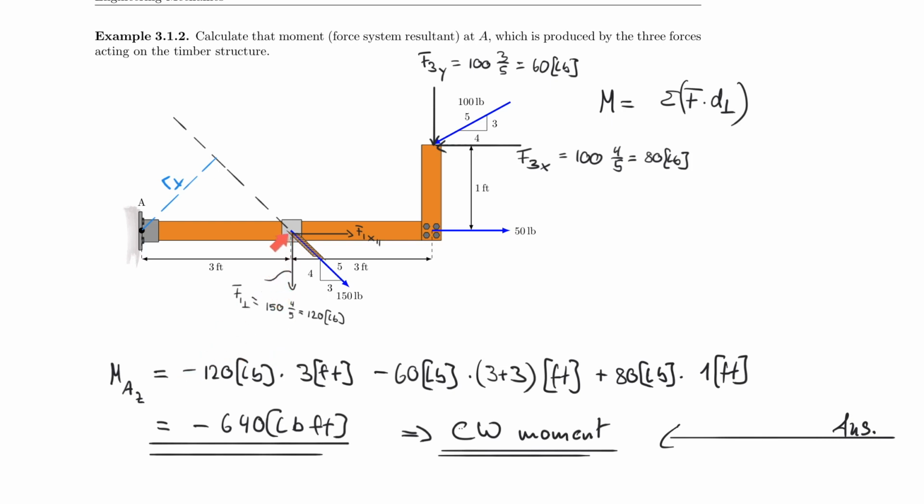So it only matters what rotation you have about this point. And in this case, you have a force that isn't going negatively down, but it actually rotates clockwise, and therefore it's negative. And that is the reason why you see this negative. Not because the force is pointing downwards, but because the force is rotating clockwise.